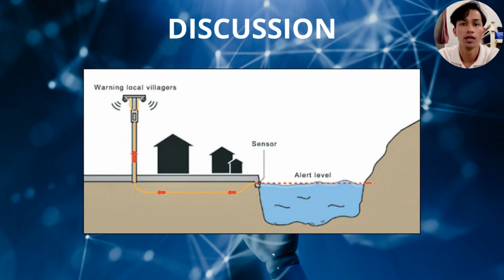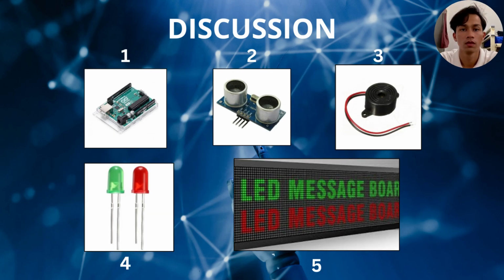In this picture, the flood alert system warns and monitors potential floods using an ultrasonic sensor. When the distance measures below 200 cm, it triggers warning indicators. These include a gradually increasing buzzer volume and a high-visibility LED turning red. An LCD display shows the distance, allowing users to track the flood threat in real time. When the distance reaches 200 cm, the display shows danger, flood, urging immediate action. The system's comprehensive approach enhances safety and enables proactive measures to mitigate flood impacts.